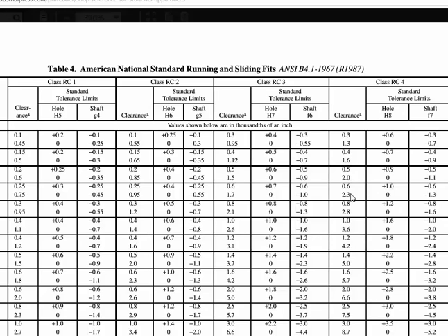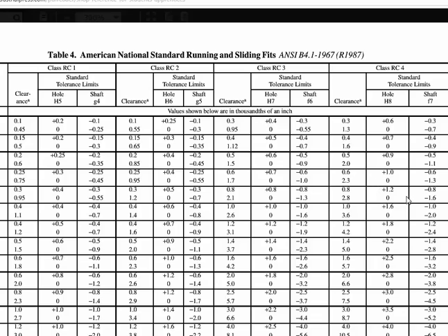The first just indicates what the maximum clearance and maximum interferences are. But as far as calculating the size you want each part to be, these are the numbers you're going to use to determine the tolerance range. So we have a 625 thou nominal size for both the shaft and the hole. Now they can't both be made that size, so now we come over here.